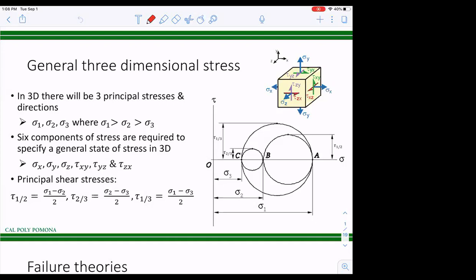Okay. What Parnian says is partially correct. If you only have loading in one direction, yeah, you could, because in other directions it is 0. But plane stress condition is when you have no loading in the out of plane direction. That means if you have XYZ, for example, and you have stress only working in the Y direction and X direction and 0 stress in the Z direction, we will call that a plane stress condition. And most of the time, you can assume the problem to be a 2D problem, all right?